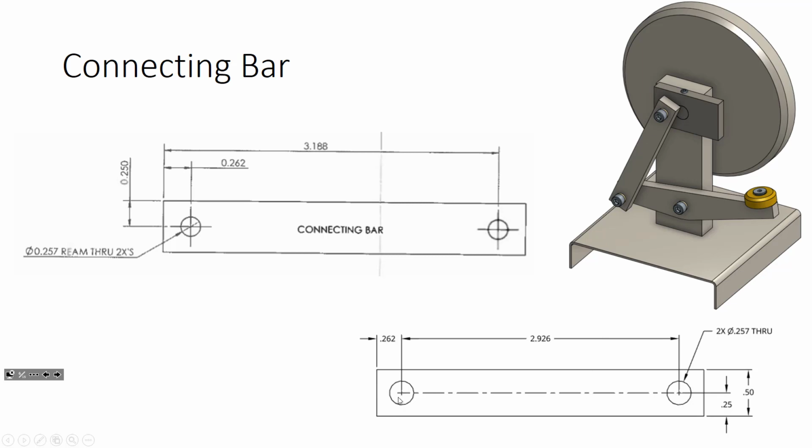So these holes are located center to center, distance to the left. This connecting center line here allows us to apply the 0.25 dimension once, so that applies to both. And that 0.25 is relative to the overall height. The 2x shows that we have the same hole diameter listed here twice, but it goes all the way through. Again, nothing's assumed. We're explicitly stating all of the information.